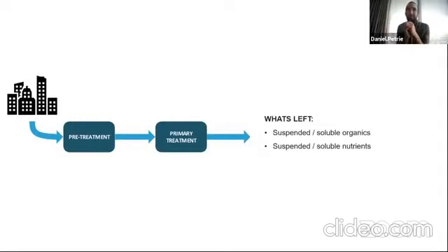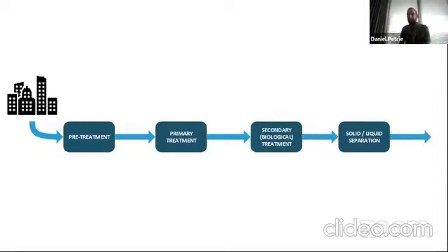So what's left? Now you've settled out and screened out all the coarse stuff. What's left is some fine particulate matter that's suspended. And you've got dissolved material, which is all in the liquid phase. So that gets us to what's called secondary biological treatment. That's probably nearing on 100 years old in its use around the world. And then some solid liquid separation.